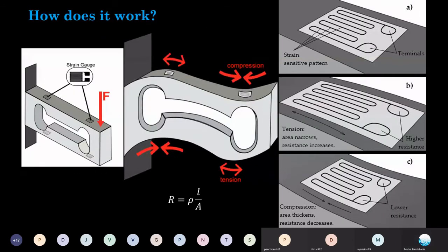In that, at 4 different locations, we have the resistive sensor that is called a strain gauge. Now this is called a strain gauge. So we have attached 4 strain gauges at 4 different locations. That strain gauge can be attached by means of some adhesive material to this load cell.